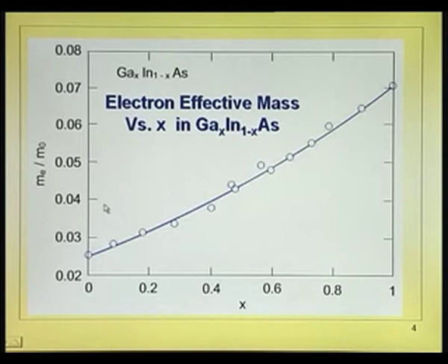You can see indium arsenide has got very low effective mass, 0.025 ratio of effective mass to the actual mass, compared to 0.067 actually for gallium arsenide. It is much lower. It is just information that I am putting across to you that as x, that is x in the gallium indium arsenide, increases, you get lower effective mass, higher mobility.